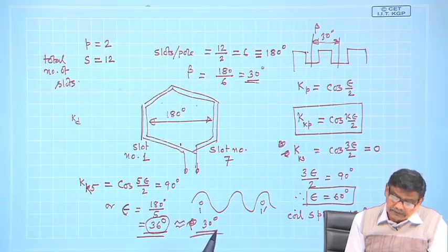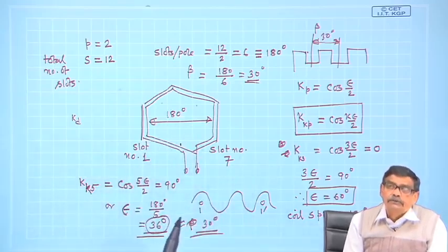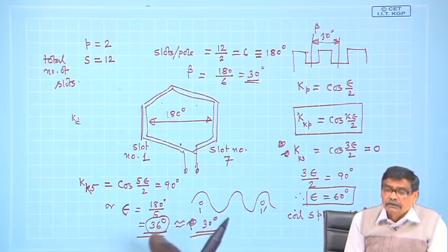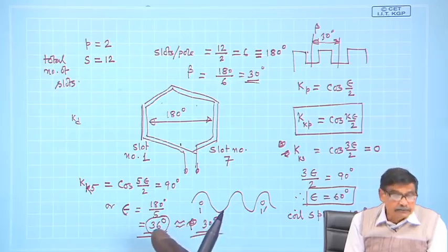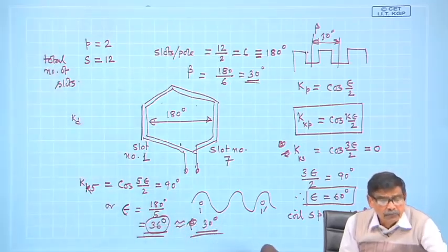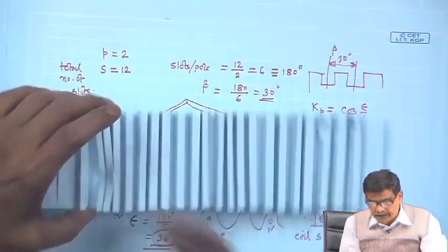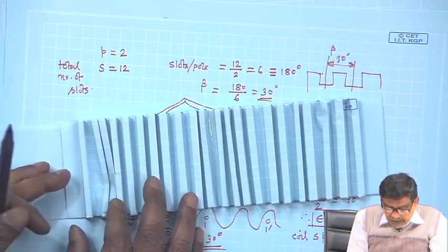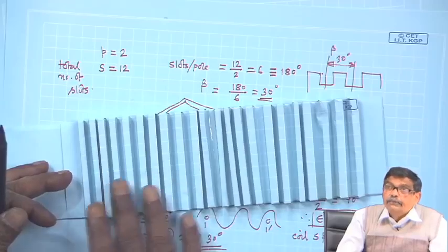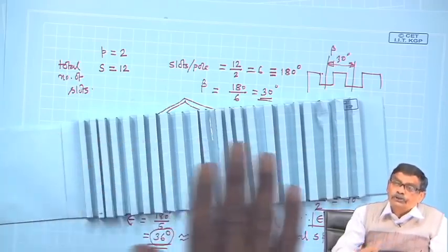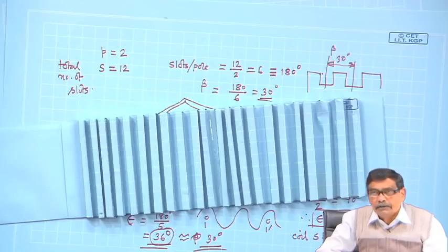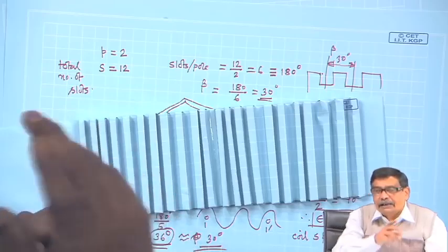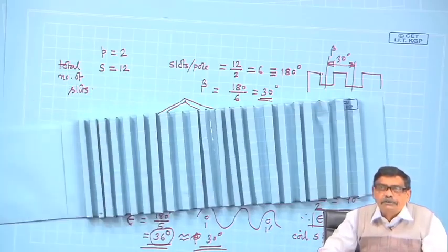Therefore, after studying these things, we conclude that it is necessary to distribute the coils. Why is it necessary? Distribution of the coils primarily means that you use more of the slots, to distribute the coils, that is one aspect. Second aspect is, if these coils are distributed, when they carry current, they will also produce an approximately sinusoidal B distribution, because a single coil gives a single rectangular MMF distribution or B distribution.